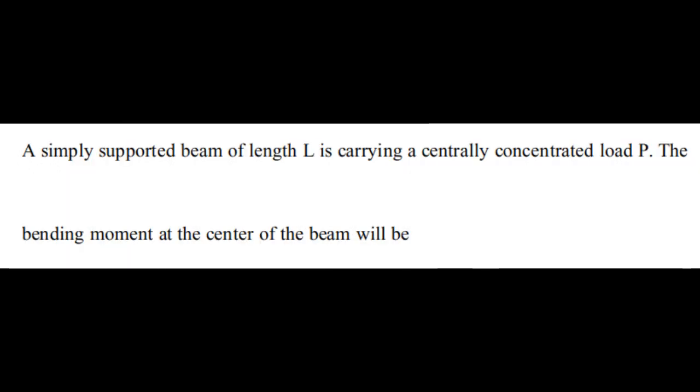Let us see past year GATE question papers. The first question is, a simply supported beam of length L is carrying a centrally concentrated load P. The bending moment at the center of the beam will be? The answer is PL by 4.